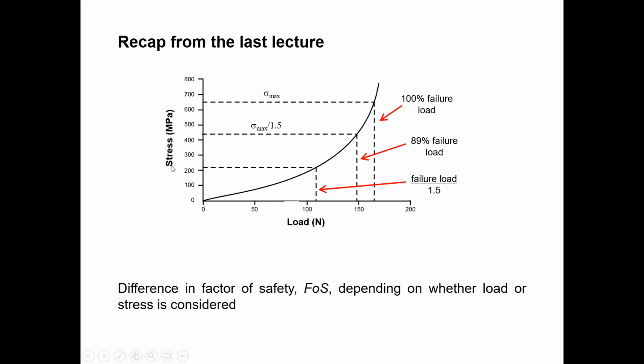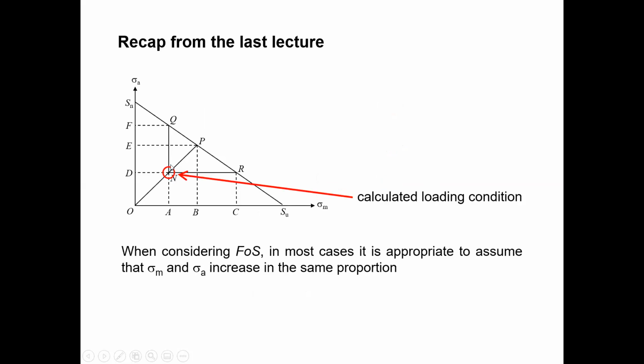If it is linear, even though you can use load or stress, you will get the same value for the factor of safety. But if it is non-linear, you can't use the stress value to find out the factor of safety. Keep that in mind. So if it is non-linear, you need to find this value and calculate the factor of safety.